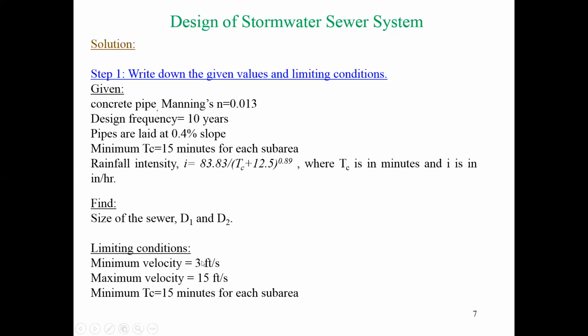And there are a few limiting conditions. Though the minimum velocity and maximum velocity are not given in the question, we already know that the minimum velocity is 3 feet per second and the maximum velocity is 15 feet per second. And the other limiting condition was a minimum time of concentration of 15 minutes for each sub area.